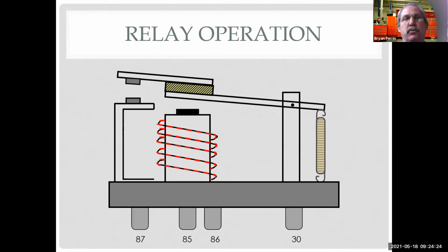I need to be able to turn them on and off when I want them, but not allow them to be on if the high beams aren't on. So I let the high beams control one side of the load and my manual switch control the other side. That's how I control this. This is getting power straight from in front of the battery through a fused circuit, and then this is going to go down to my lights.